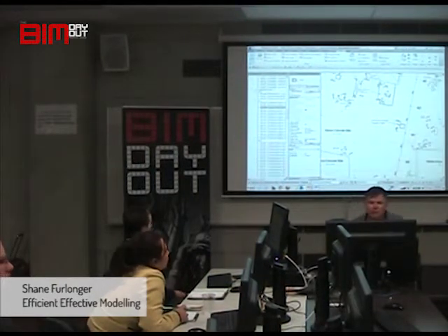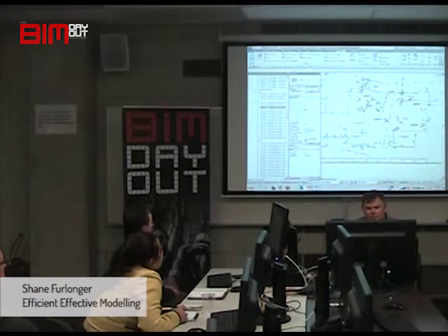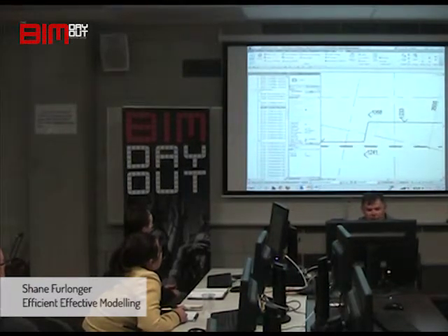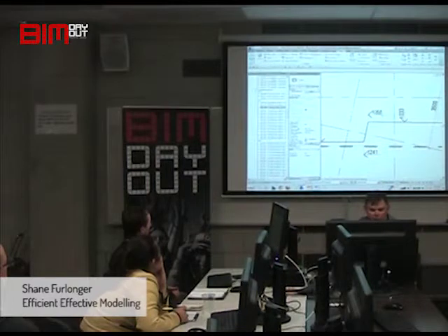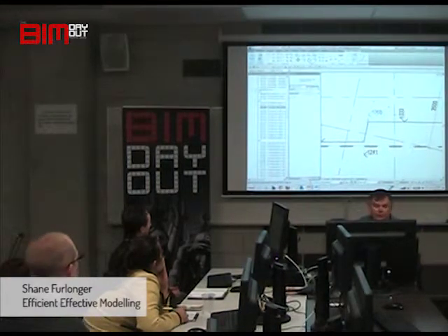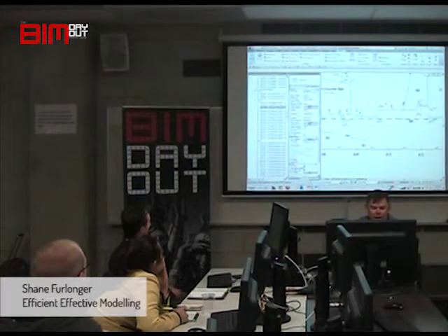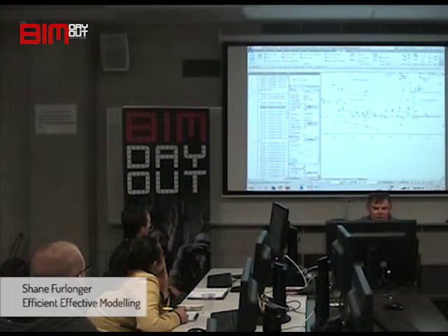I was saying before about the running dimensions. I just wanted to quickly show you. This is a concrete floor set-out plan. And this is a running dimension. So it goes from the grid line. Actually, I'll just activate it here. It goes from the grid line to the point that you want to dimension, and it's exactly where it needs to be.